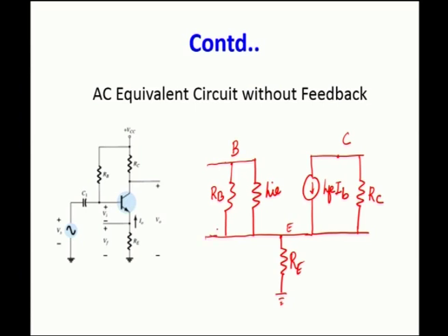If we have a capacitor also, we have to short the capacitor, we have to neglect it, and since we have a capacitor in the power supply also, we are neglecting it. We have to consider all these as common points. So, we have to consider only the resistances and the forward current transfer ratio, that is the internal hybrid parameters of the BJT.